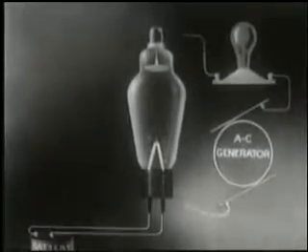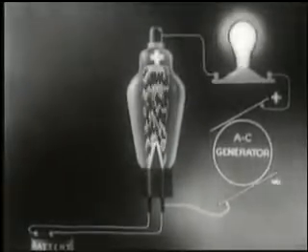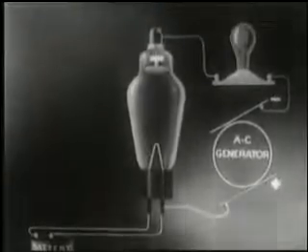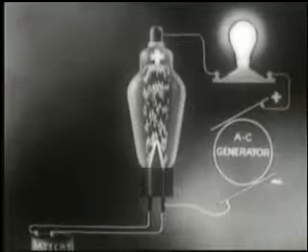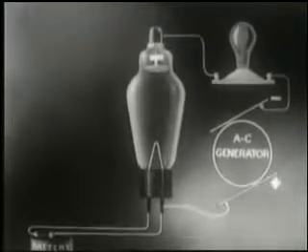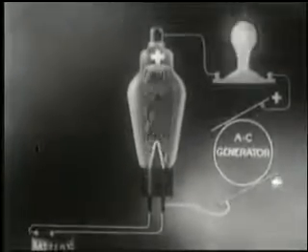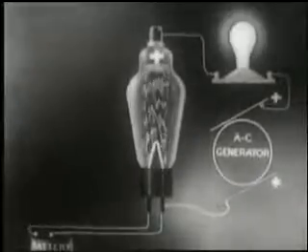We can do this merely by connecting an electronic tube in series with an AC circuit. As you study this circuit diagram, note that only each positive half wave of AC voltage will now produce a current. When the anode is negative, the electrons are repelled and no current flows. In other words, because only the cathode can emit electrons, we have here what amounts to a one-way street.